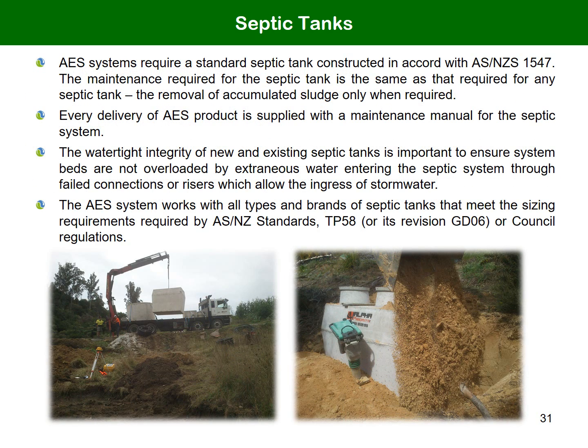A single compartment septic tank is required and should be installed with sealed connections to prevent ingress of water from the surrounding soil. The AES system works with all types and brands of septic tanks that meet the sizing requirements required by AES New Zealand standards, TP58, GD06 or other council regulations.